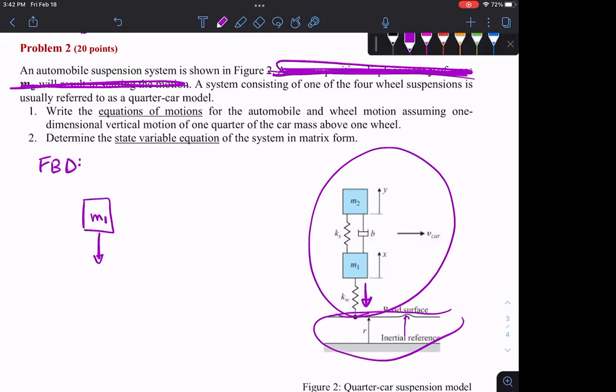So here your input is kind of a disturbance, if you think about it, right? It's an input, but still something you don't like. So it's K_w of some displacement, right? So the displacement is, X and Y are your position at equilibrium. Your car was moving, so the lower part is your wheel, the top part is the chassis. So you're moving and both of them are holding their position, X and Y. Then you hit the bump. So you start moving from here.